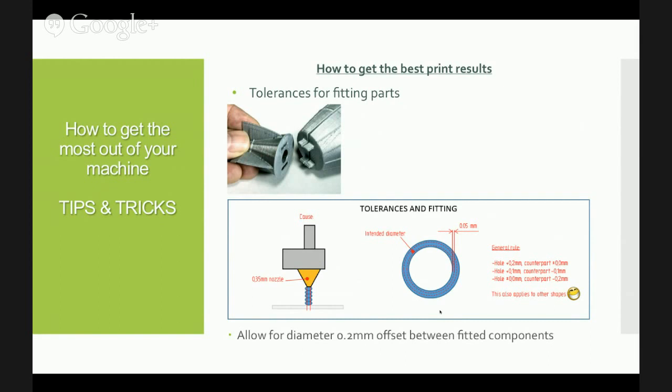It's not pushing it on 0.35, but it's pushing it out a little bit. And if you have a circle, for instance, you can see it in the second picture, it pushes it inwards a little. So a circle will also always have a little bit smaller inner diameter and also have a little bit bigger outer diameter. You can account for that by making your model already bigger or smaller, so you can have an absolutely right amount.